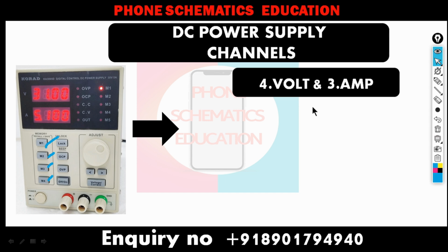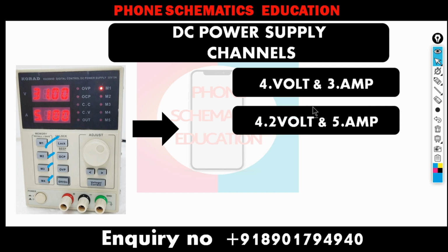Right, now second, 4.2 volt 5 amp. Sometimes I'm using this also with the multimeter probe. I use the multimeter probes, right, if I find a short circuit in a primary line, then I use this one attached with the multimeter probe. That's on 5 amp, and we find the short in a few seconds.